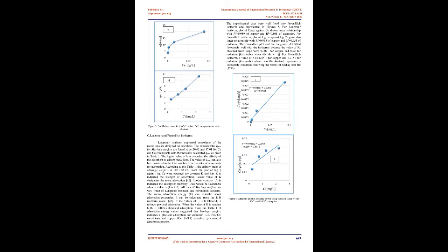Equation 4 could be expressed in a standard format as given below, where Ce is the equilibrium concentration of sorbate, mg/liter or ppm or g/cm3 or mol/m3, Qe is the amount adsorbed at equilibrium, mg/g, while Qo and b are the Langmuir constants related to capacity, mg/g, and energy respectively. A plot of Ce/Qe versus Ce gives a straight line of slope 1/Qo and intercept of 1/Qob.